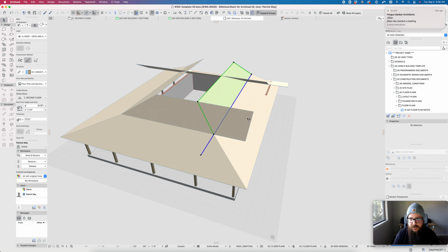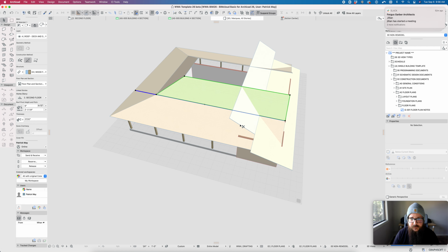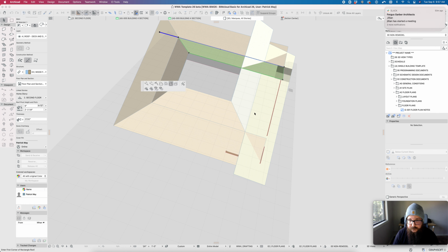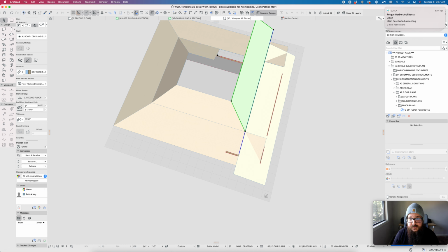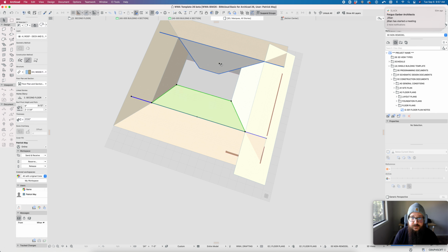And some of these have to be done one at a time, so it is a bit more tedious. But it is possible to trim these out to each other really quickly once you get the hang of it. And it's not just extending backwards. For example, if this roof, let's pull this to here, I need to find where this joins as a hip to that roof. I can Command click there. And it works for hips, it works for ridges, it works for valleys. So here I can Command click this up to here and this up to here.